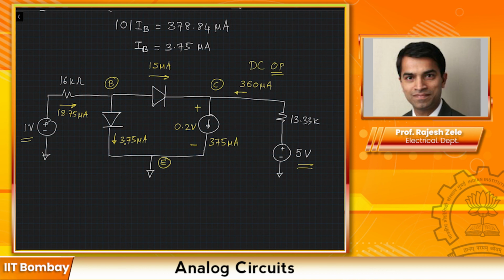So what we do is a large signal analysis and figure out which mode the transistor is in. Make sure that all the terminal voltages and current conditions are met. Based on the large signal analysis, we figure out the small signal parameters, and the small signal model is what we use to figure out the small signal gain of the amplifier.